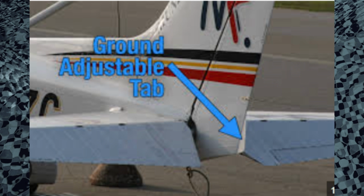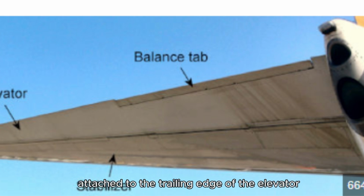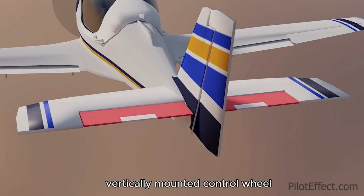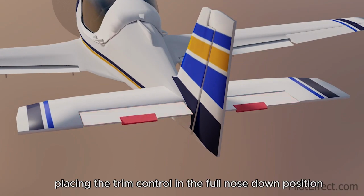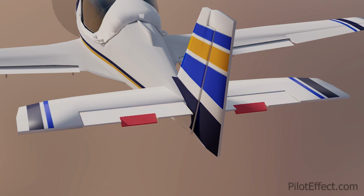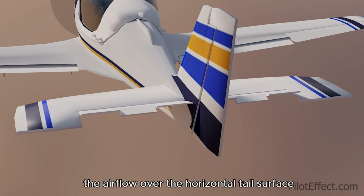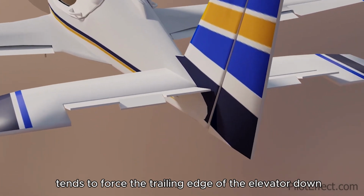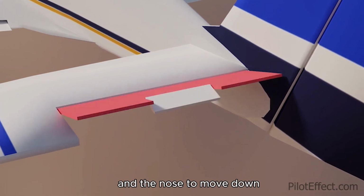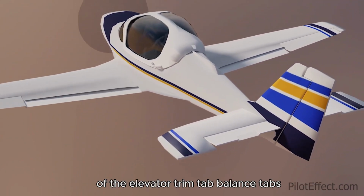Trim tabs. The most common installation on small aircraft is a single trim tab attached to the trailing edge of the elevator. Most trim tabs are manually operated by a small, vertically mounted control wheel. Placing the trim control in the full nose-down position moves the trim tab to its full-up position. With the trim tab up and into the airstream, the airflow over the horizontal tail surface tends to force the trailing edge of the elevator down. This causes the tail of the aircraft to move up and the nose to move down. The movement of the elevator is opposite to the direction of movement of the elevator trim tab.